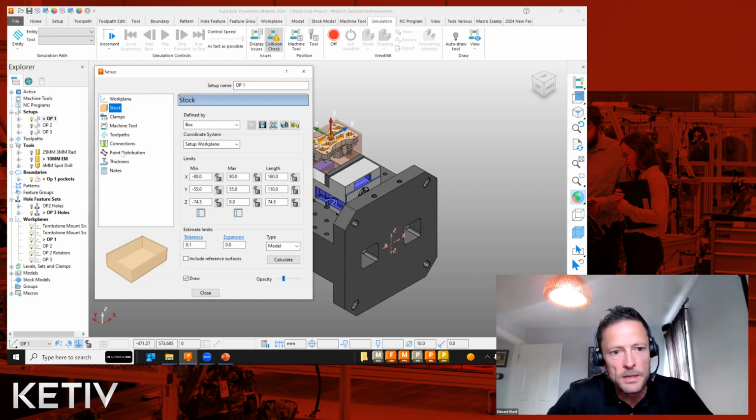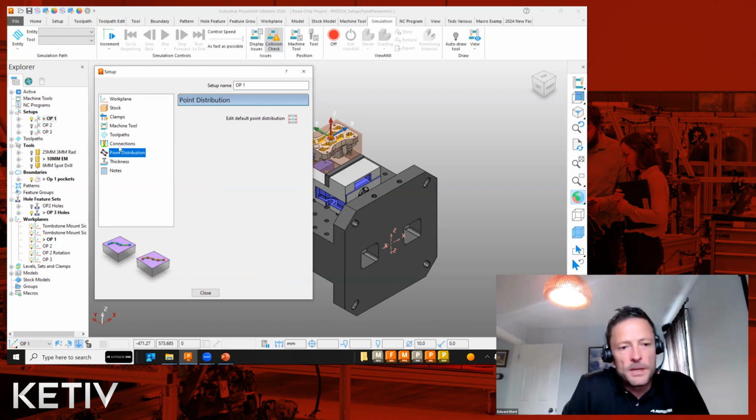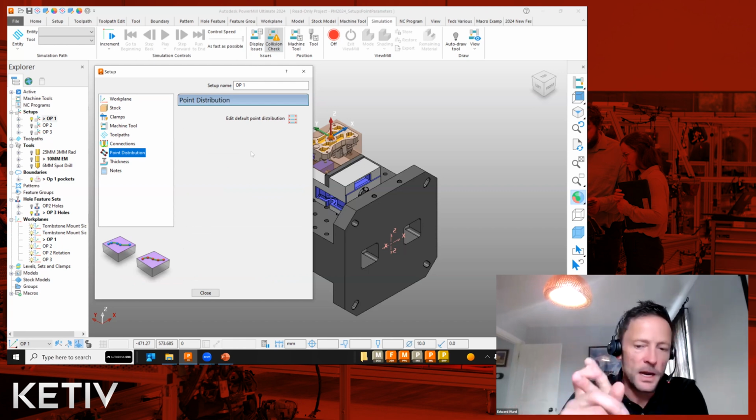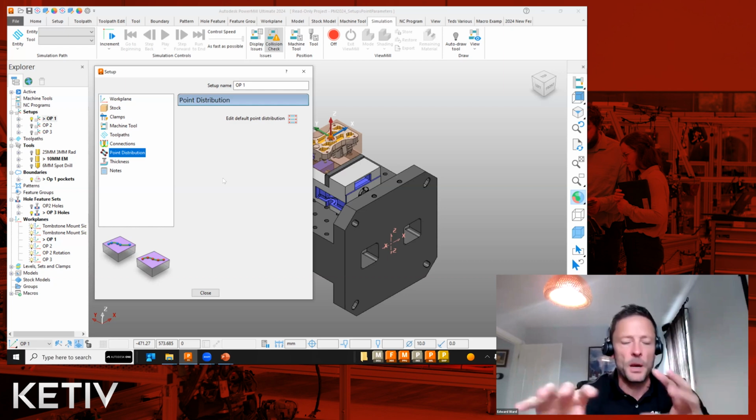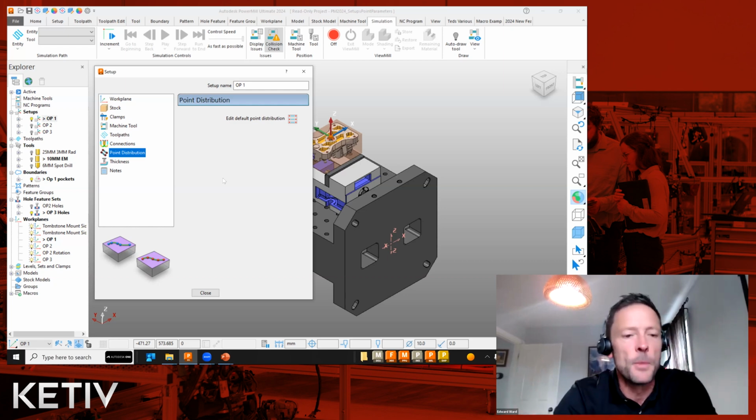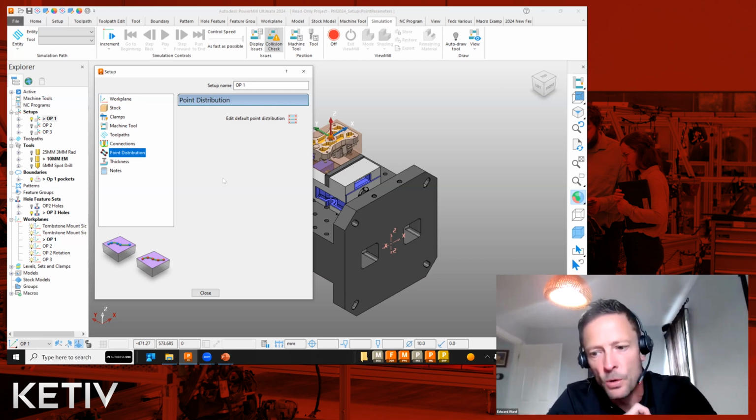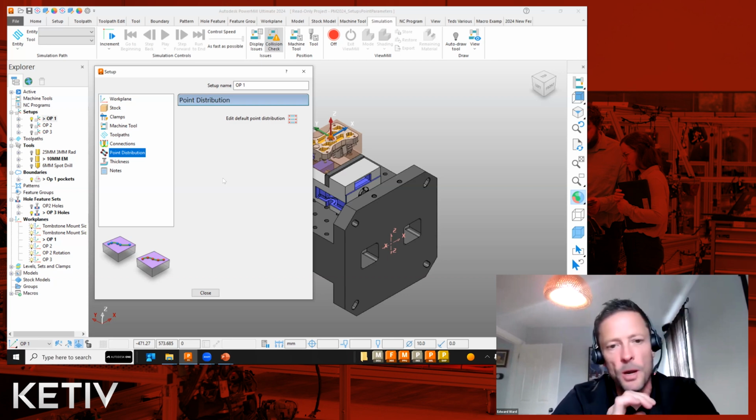So it would be one more thing that we'd have to change. But I can set these rules ahead of time for a particular setup, call it top, and every toolpath follows those rules. Then I can create another setup, and we can have all of the things like machine simulation, your important things that used to jump around all the time. We found ourselves having to manually modify them afterwards, things like your simulation work plane or your output work plane.